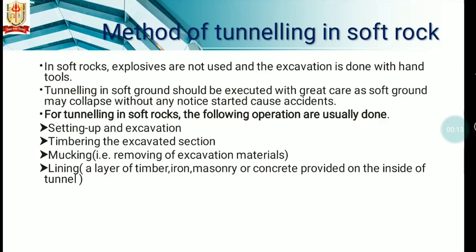Now start the next part, which is methods of tunneling in a soft rock. In a soft rock, explosives are not used and the excavation is done with hand tools. Tunneling in a soft ground should be executed with great care, as the soft ground may collapse without any notice and cause accidents.